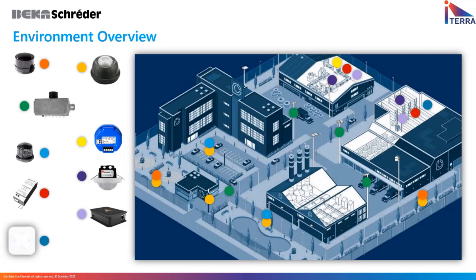We look at ablutions. Many times lights in ablutions, especially for large areas where a lot of people are used, those ablutions are big, and those are on 100% all the time. So again, looking at what budget the client would have, either use extra hardware or cleverly use timing to switch things on and off during a specific time of day. And the nice thing is this becomes a network.